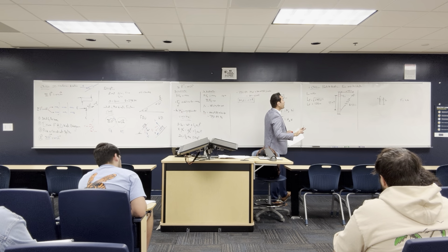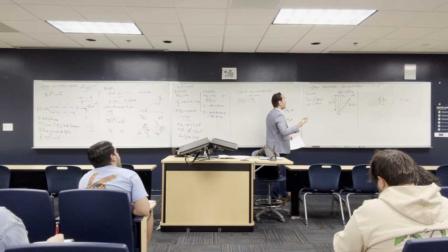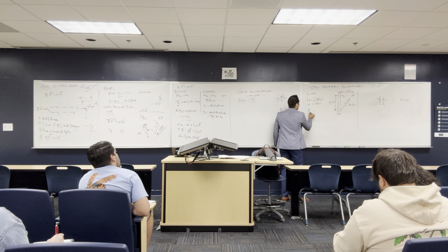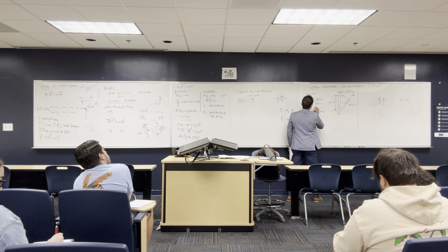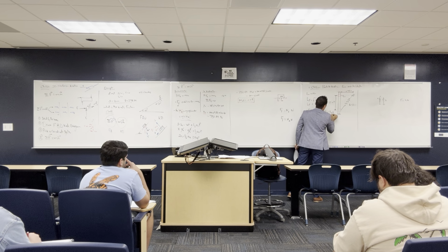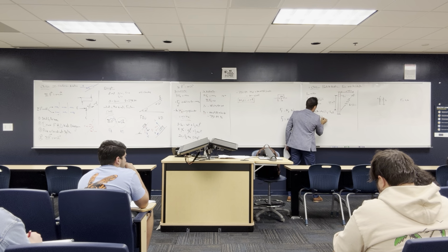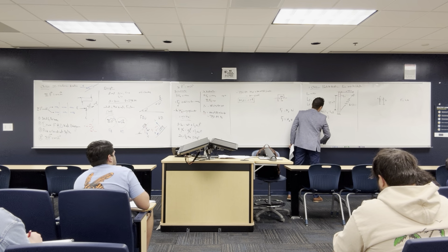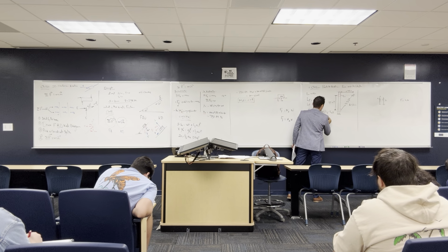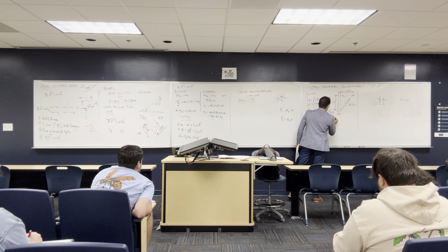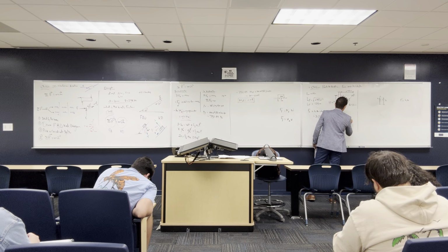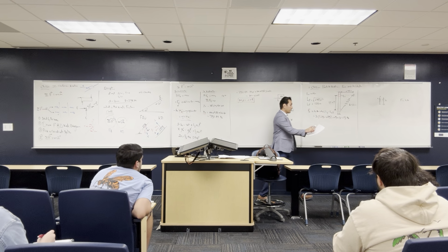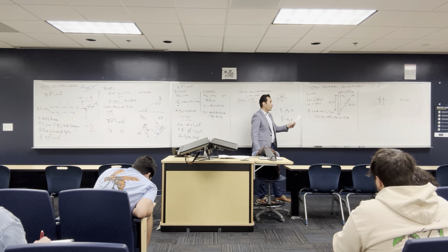Okay, so I know right now what is the L final, what is the L initial. So right now I can know what F spring is equal to. How? By multiplying K by delta, K of the spring. I know it's 3, and delta is L final minus L naught, so this is going to be 3 times 1.25 minus 0.75. So this is going to be 0.5 multiplied by 3, equal to 1.5 Newton. The F spring is equal to 1.5.